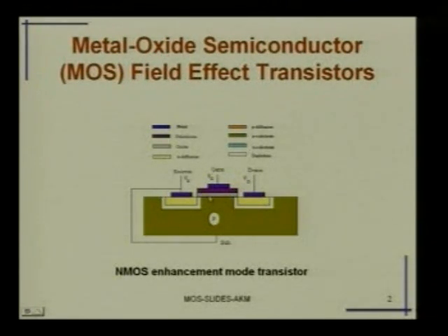A very thin layer of silicon dioxide is deposited by many methods; it can be done by chemical vapor deposition or by other techniques. We will cover those when we go through the fabrication aspect. On top of it we put the electrode, that means metal deposition. This black part is a metal.